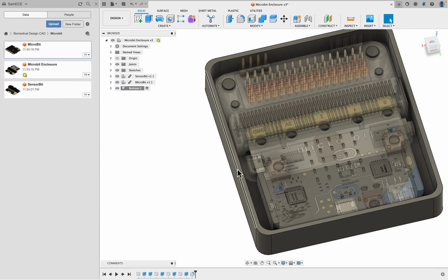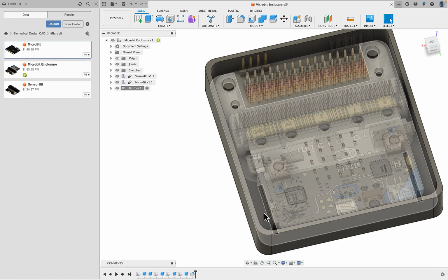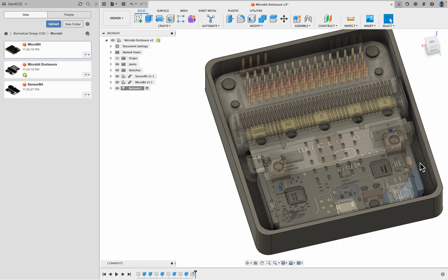Another way to go, which I often employ when I do manual things, is to use screws and bolts in order to hold it into place. And in this case, I'll just find some areas. This one, of course, would be ideal because that's actually a hole, so we could do a bolt from top to bottom. But since you might not have access to M3 bolts, let's just do a soft enclosure where it snaps into place.